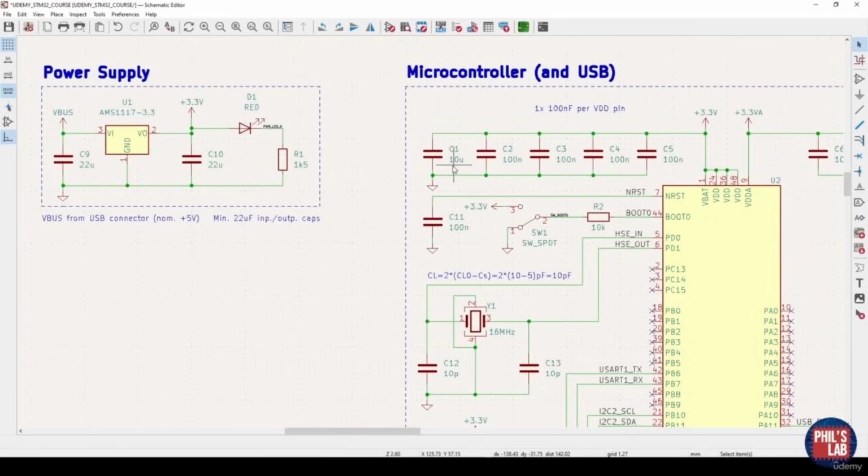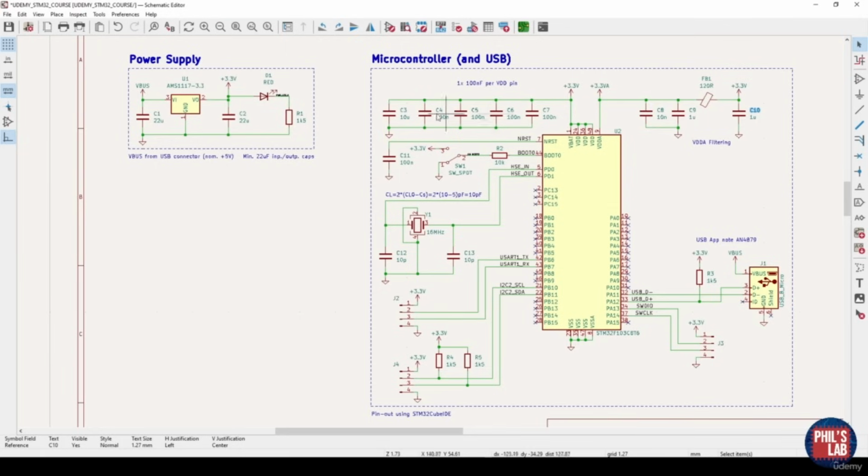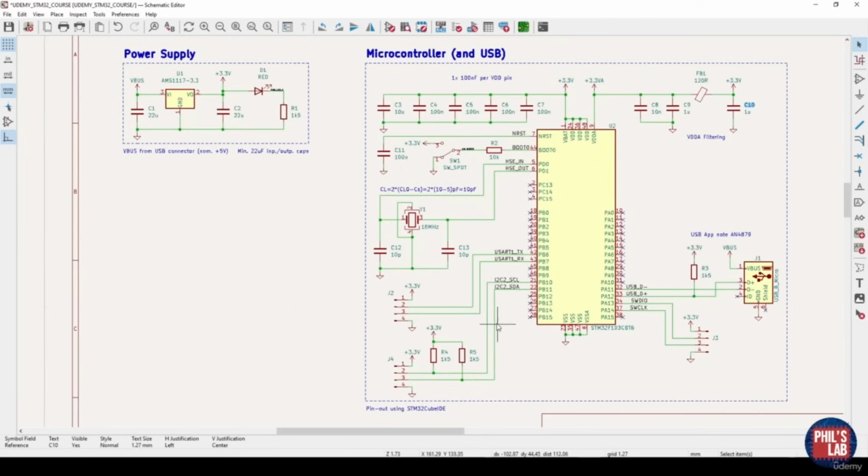And because of the alignment again, here I have C1 starting here, even though I want C1 starting here. So oftentimes, if I'm quite honest, I will just do this manually because I have my preferred way of sorting my schematics and the way I think is logical. So let me just do that. So now I've briefly gone through and annotated my designators. So I start over here, C1, C2, C3, C4, and then move down. So first of all, kind of section by section, and then top to bottom. Same thing with resistors, connectors, and so forth.